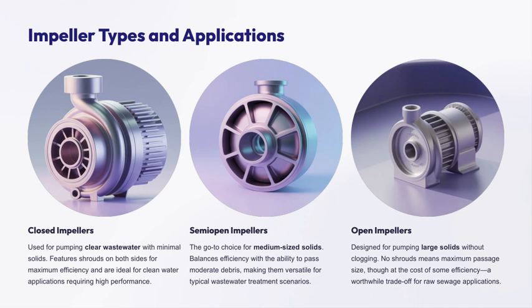You'll find they are ideal for situations where clean water is required and high performance is essential. Next, we have semi-open impellers. These are quite versatile and are the go-to choice for medium-sized solids. They strike a good balance between efficiency and the ability to pass moderate debris, making them suitable for many wastewater treatment scenarios.